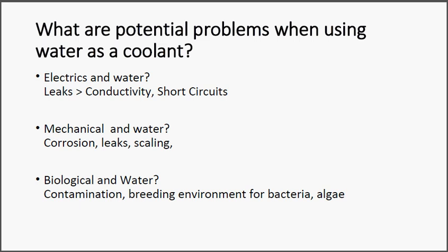Okay, when we look at mechanical systems and water, even though it makes perfect sense to use water, as there's plenty of it around, one problem is scaling. If you've got lime or something dissolved in water, it could leave deposits inside the cooling system. And then the next one is corrosion. This is a big problem in mechanical systems.